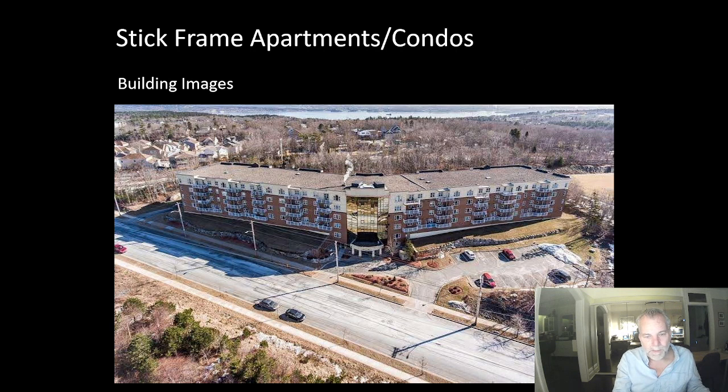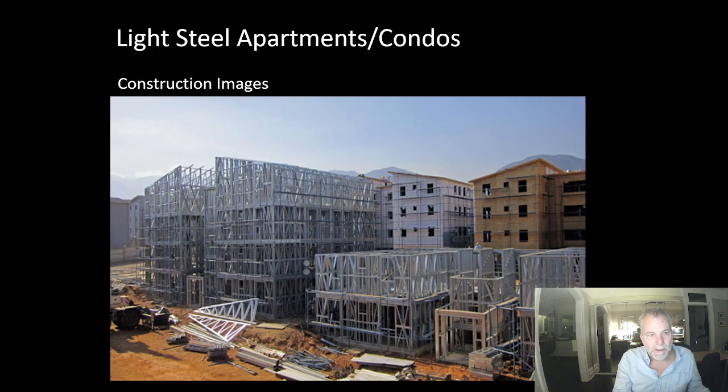So you can see we can wind up with some very large buildings in light wood frame. This is light steel frame. And you can see that it looks very much like light wood frame, except that the elements are silver instead of amber color. One difference is you can see there is no sheathing. In light wood frame, the sheathing, the panel product on the outside, is not what's carrying the lateral loads. You can see a bunch of X's on the walls. Those X's are steel straps on the outside face that get screwed to the studs. And those straps act like X bracing in our building.